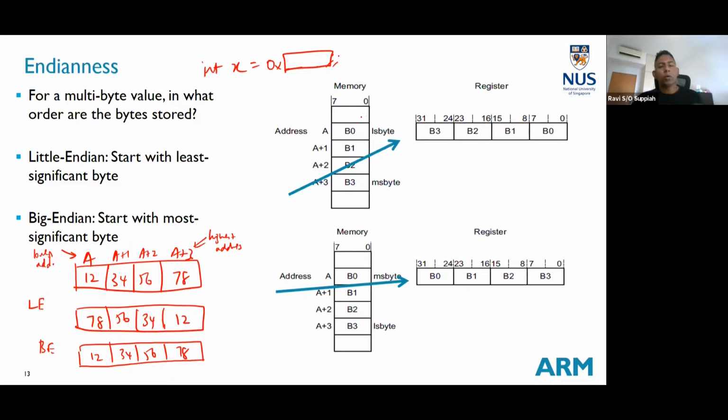But if now I go to the memory location and I want to read byte by byte, so instead of taking it as one full 32-bit or 4-byte value, I want to extract a particular byte, then I need to know which address to go to. That is where this understanding of endianness comes in. You need to know exactly which address that particular byte is stored in. We will see that later on once the programming starts.